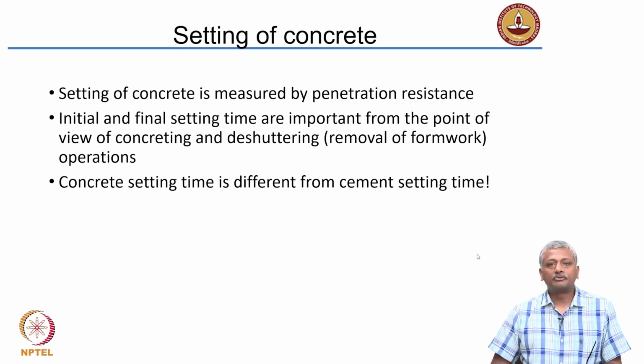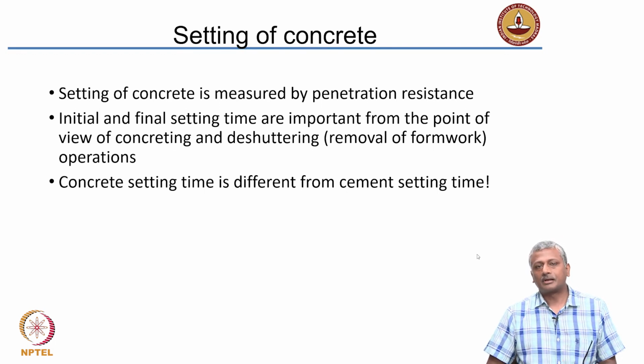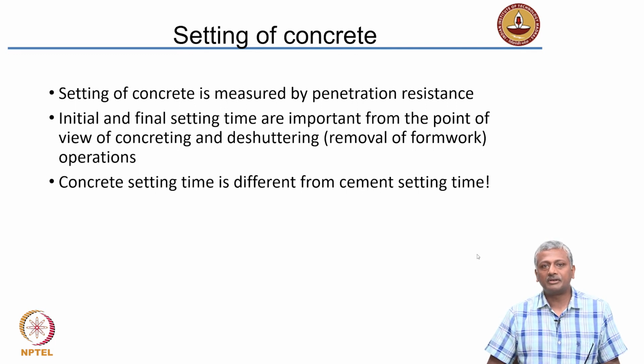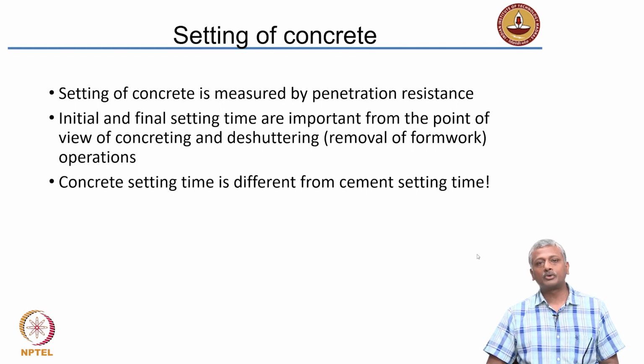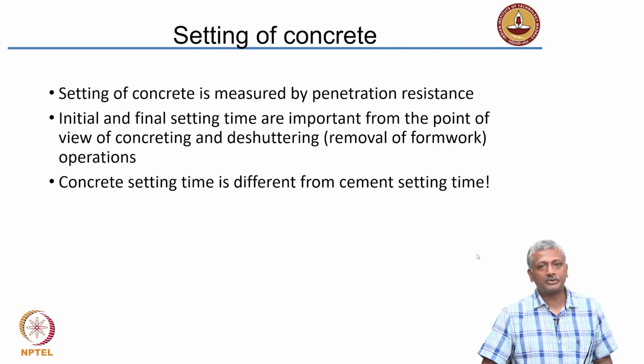Now, of course, we talked earlier about the fact that cement hydrates by reacting with water, and slowly this leads to the setting and hardening of the cement itself. Now, please remember that concrete is a conglomerate which is made with cement, water and aggregate. So, the way that the concrete sets is not exactly the same as the way that the cement sets. Please remember, in cement we talked about the use of the Vicat test to determine the setting time of the cement.